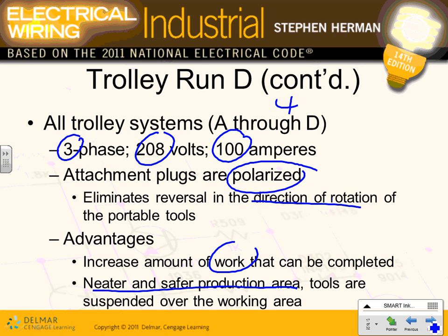So what they did here for the plug-in, they took every 225 amp and they broke it up for one reason: maintenance. Number one, if you have a short circuit in one section, you don't want to take down everything else. So from a maintenance point of view, from a diversity of the load, it's a good idea to chunk them in chunks of 100 amp or 225 amp, like plug-in busways. That's all. So for maintenance, the same thing.